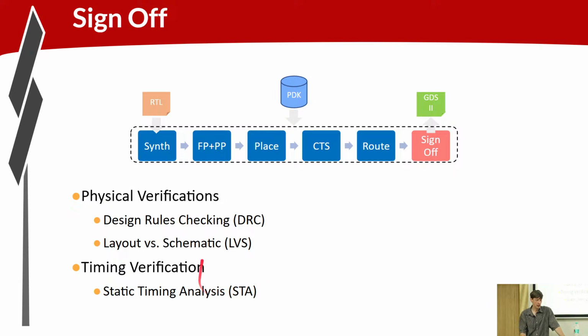After you have your design, you want to make sure, this is kind of the verification step, to verify that the tools did what they're supposed to do. If the tools are all working and doing their job, the check sign-off shouldn't be an issue, but we want to check the tools. So we do various back-end checks after we have this. And then we have our GDS2 file, which we can send off to get fabricated.